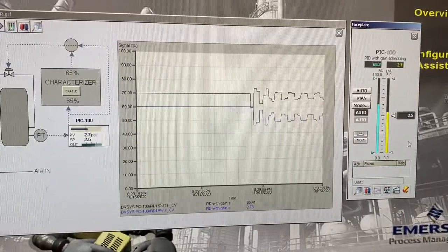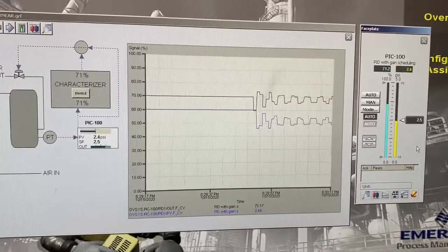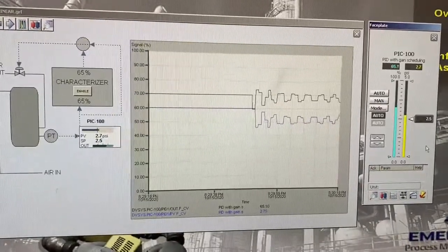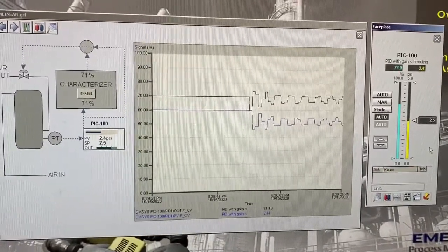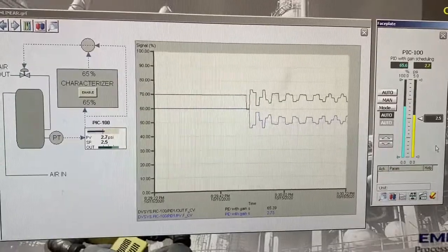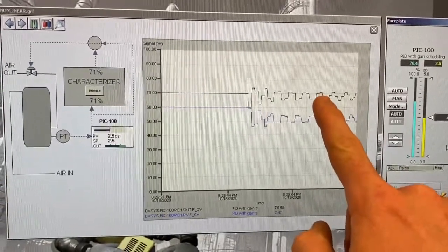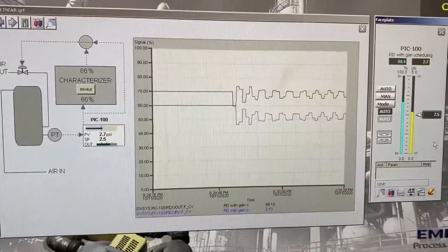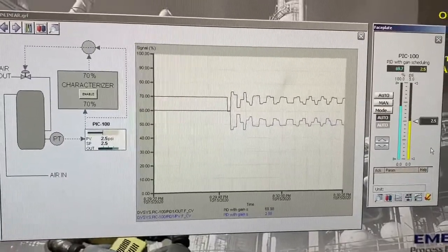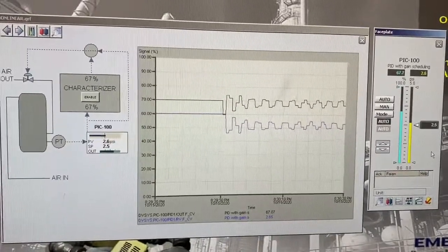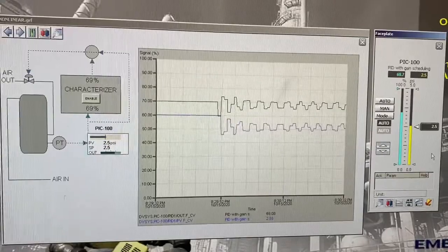And it looks like they're pretty close, yep. I'd say they're not really growing or diminishing yet. And it looks like our period of oscillation here again is about that 4 seconds. So it's about the same period of oscillation, but our proportional gain here is only a value of 1.